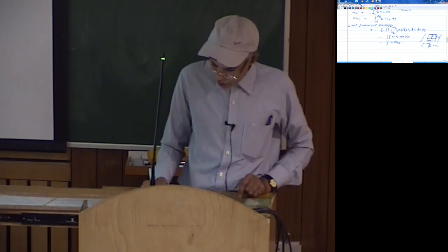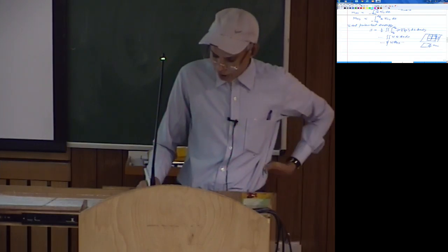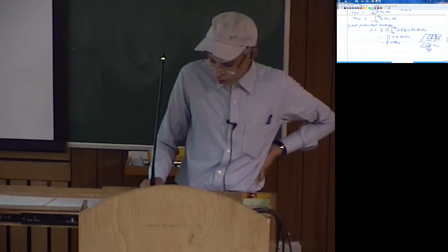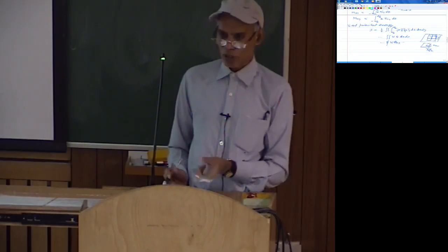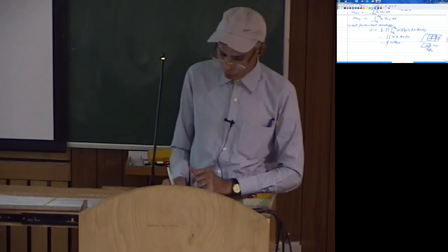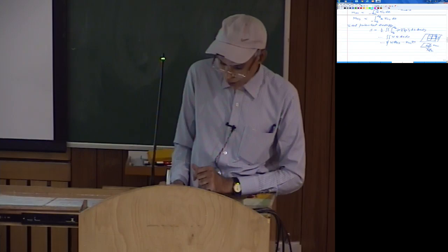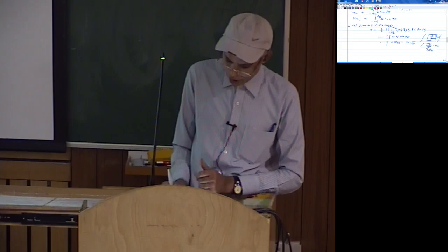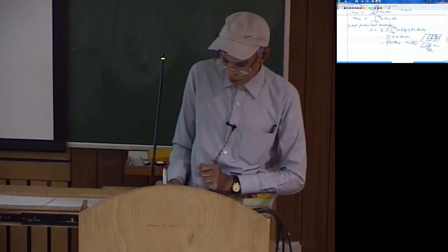As far as the rotation about this boundary is concerned, del w by del x is like del w by del n, which will be the rotation about this axis. By the definition of moment resultants and the rotation, they are going to be of opposite sign. So I am putting here m n n into del w by del n. This is the moment and this is the rotation, which gives you the work done. And since these are in the opposite direction, work done is negative, so the potential will be positive. So this minus will become plus, into ds.